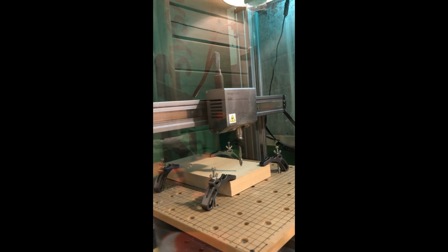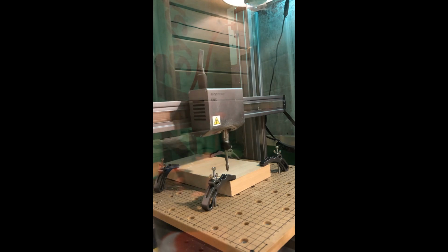Okay, now I have that set to 0. Move my feeler gauge. Go back to where my controls are at. I'm going to move my head, my Z axis here. I'm going to move that up 10. And then I can move this back over here, back up in this area somewhere about where the home position was at. And then all I got to do is say go to work origin. I'm in my work origin.